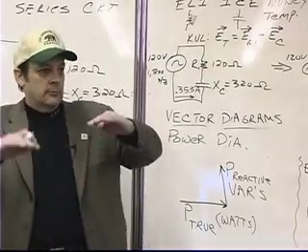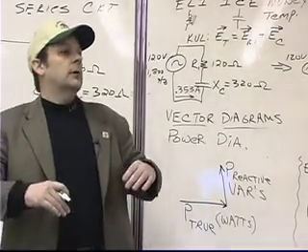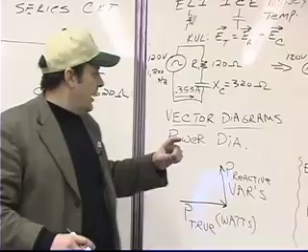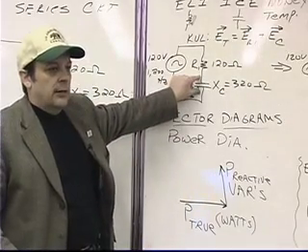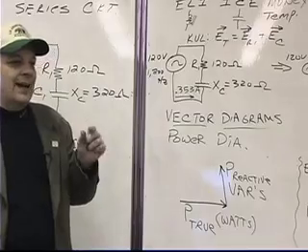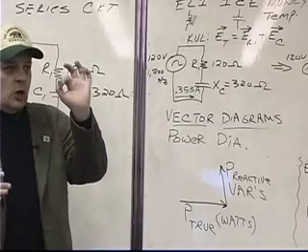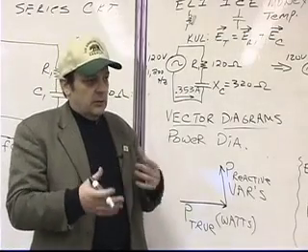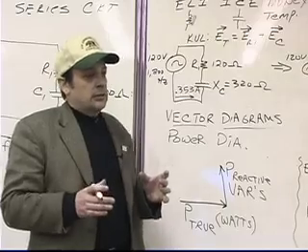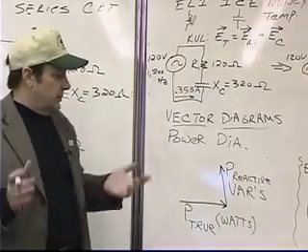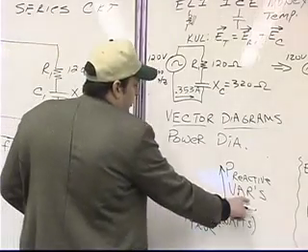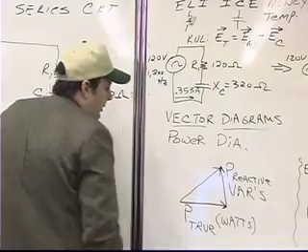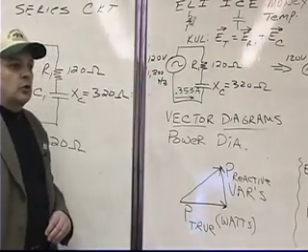So it's like a teeter-totter. You know, at one moment you're pushing up, and at another moment you're falling down, and you just kind of teeter-totter back and forth. And that's what the power in the capacitor does, and we call that wattless power because an ideal capacitor dissipates no heat. A real capacitor dissipates some heat because there's actually resistance in a real capacitor. But an ideal capacitor, which is what we model in our circuits, dissipates no heat and is measured in volt amperes reactive.